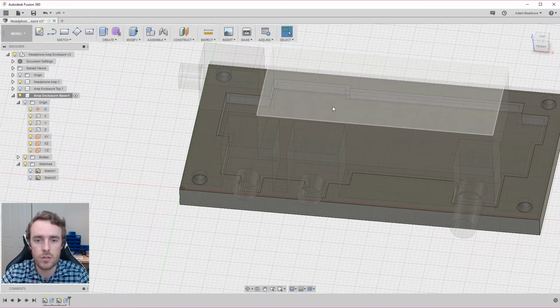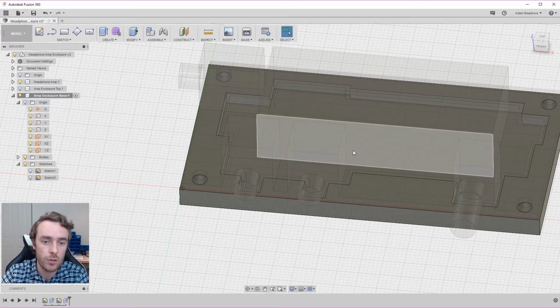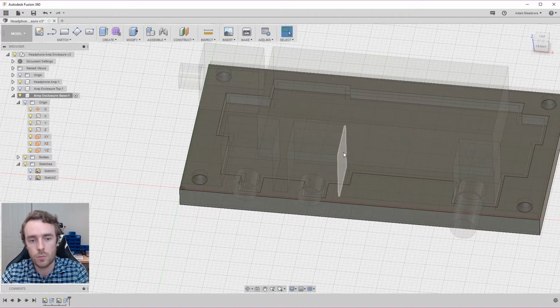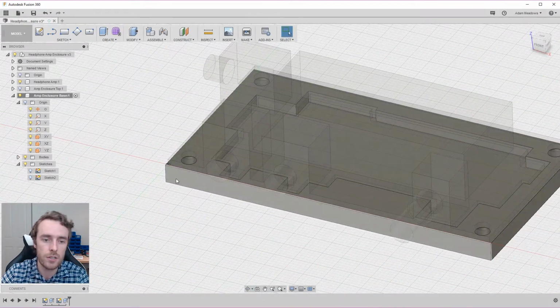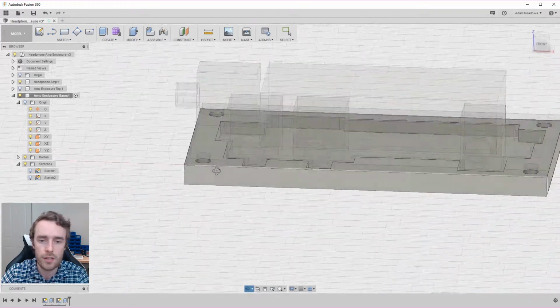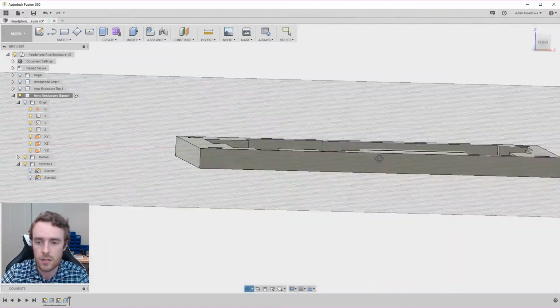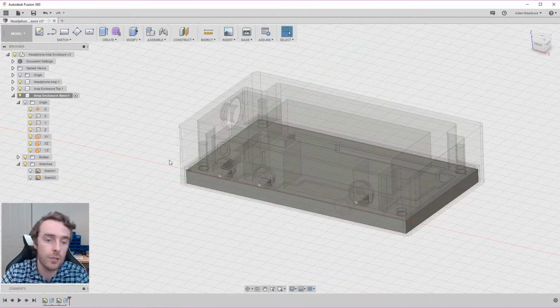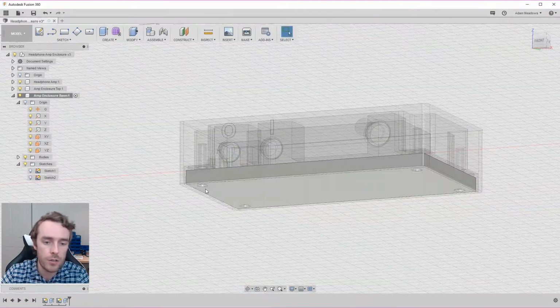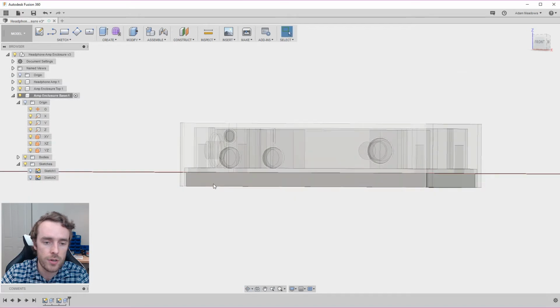We've basically used the reference geometry of the solder points to make sure when we extrude upwards we avoid them. We've got holes from the PCB and the outer distance from the enclosure, and that's given us a nice base which should be nice and solid for screwing to. That's all looking pretty good, but at the moment when you try and screw into this, your screw is just going to stick straight out the bottom.